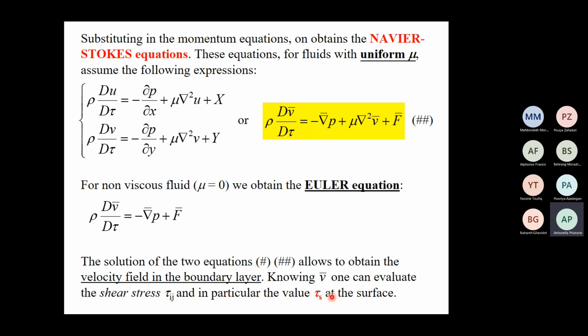For an engineer, after the equations, these complicated derivatives, the substantial derivative, the final aim is to evaluate the transfer rate and the pressure drop. If I have to size some equipment, I have to know the transfer rate and the pressure drop associated with it. Knowing the velocity field, I can evaluate the surface shear stress and as a consequence the pressure drop.